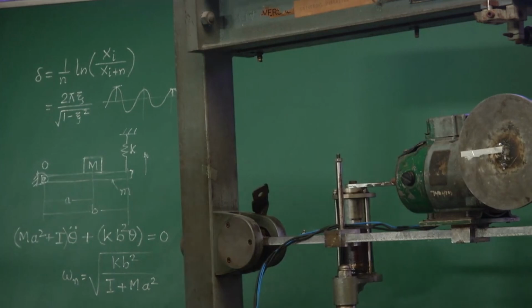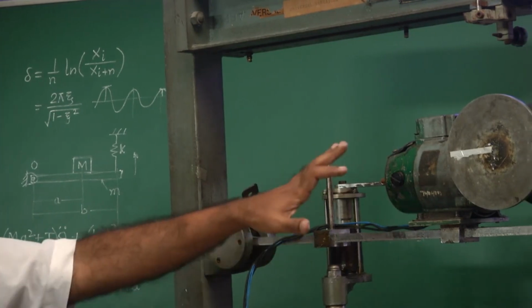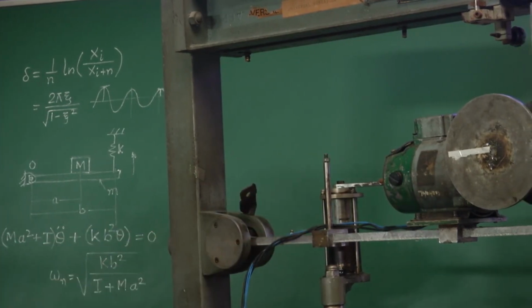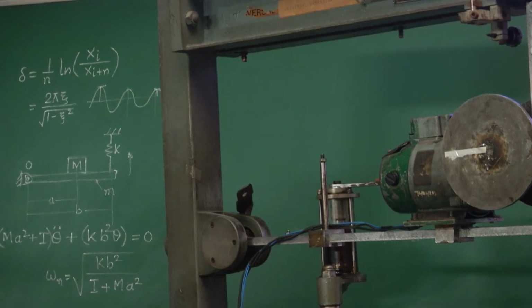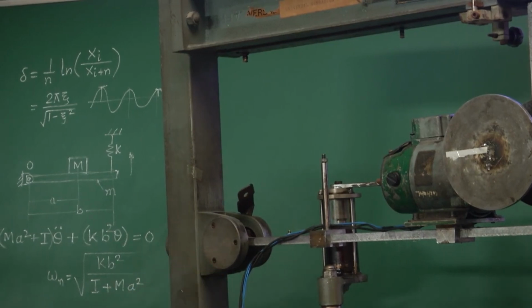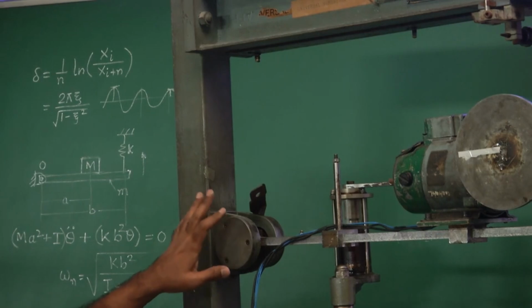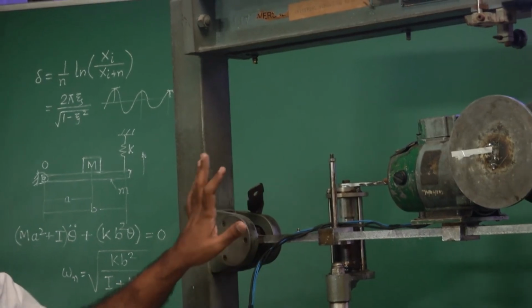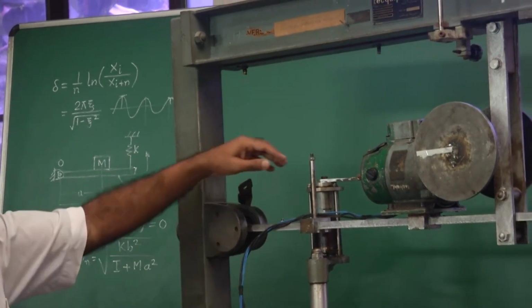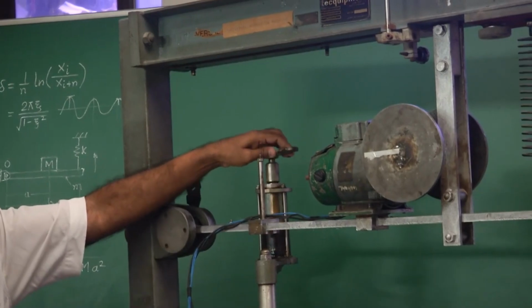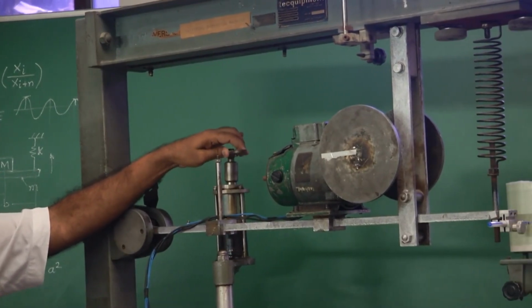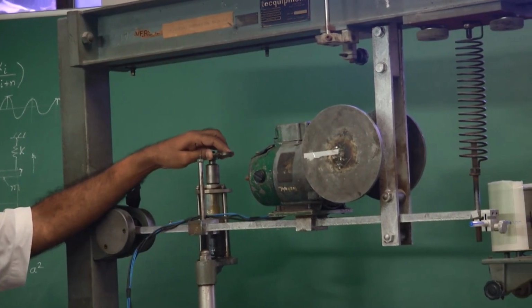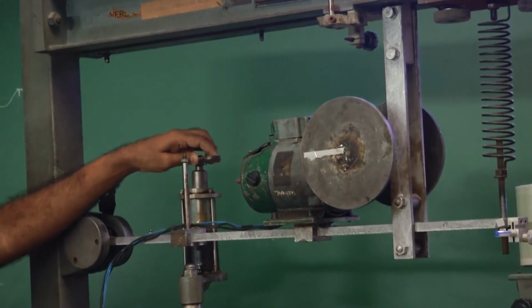So, this is what we are expected to do in this experiment, to find out what is the damping existing in the system. Now, having seen this sort of an undamped case, although there is damping, the damping is not coming from a dashpot, but from a variety of other sources as I discussed. We do have a dashpot, a formal dashpot, which is like a cylinder filled with a viscous fluid, and then there is a piston that moves back and forth in this viscous fluid.